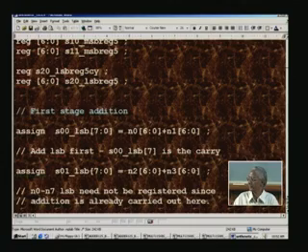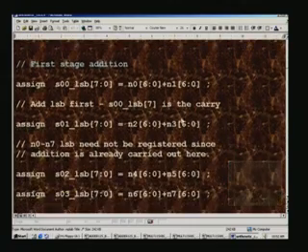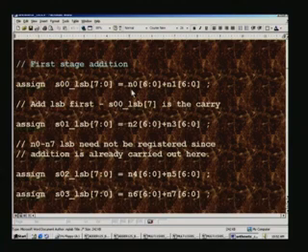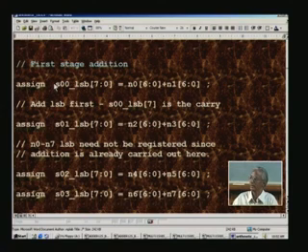And the first statement is, as we mentioned before, in the first stage we add two numbers at a time, N0, N1, and we add only the LSBs of these. So for example 7 bits only are added, and in parallel, that is concurrently, we add other numbers as well, N2 and N3, using these assign statements, and the result is declared as wire.